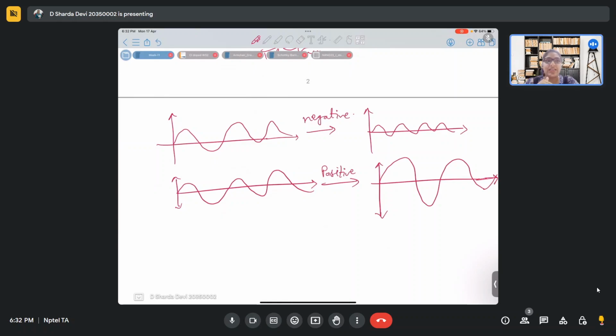When we have negative feedback, we can actually control things. So when you want a controlled operation, we always go for negative feedback. That's why in the case of amplifiers, we have many constraints that we need to meet: swing, gain, bandwidth, and all these factors need to be closely controlled. So for that close control, we always go for negative feedback. You'll never find an amplifier with positive feedback. That is one of the major reasons why we go for negative feedback.